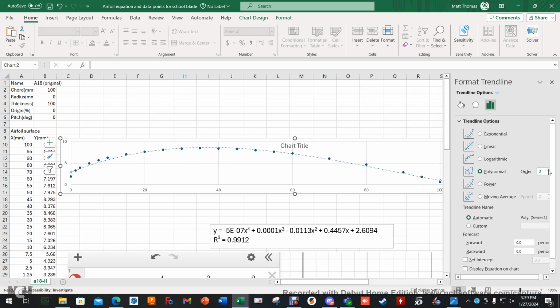So we're going to hit third order. We can see we do a little better, especially here. But right here we can even do better. We're going to do fourth order, and that's pretty good. Now if we do a fifth order, that gives us a sharper trailing edge, which I don't want for this particular case because my wind turbine blade does not have a sharp edge. It's rounded. So I'm going to go ahead and drop it back off to 4.